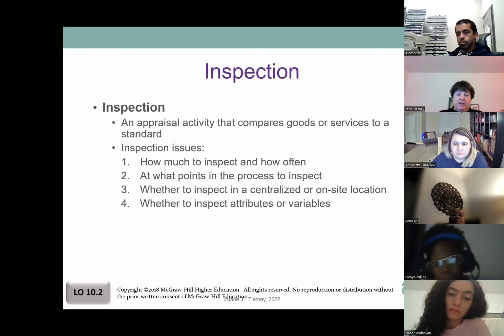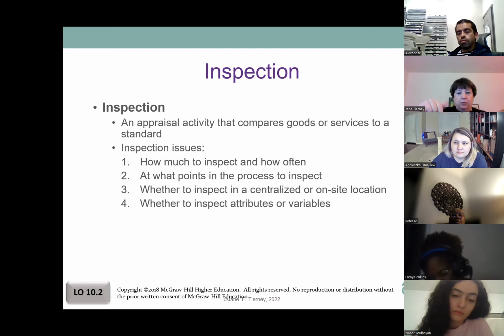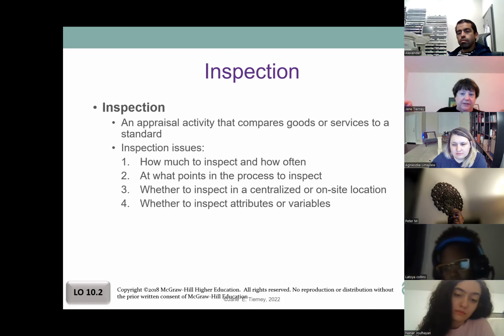Mhm. So we can measure that, we can set that up, and as Nikon said, make sure it's all even and everything. And then we could actually put something in there that we can pull out and say, hey, did it actually get to be 6 inches? Or put a little marker on the edge of it, say, 1, 2, 3, 4, 5, 6, so that when the concrete comes up to the 6 inches, we know where it is.